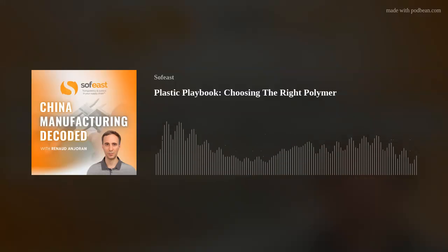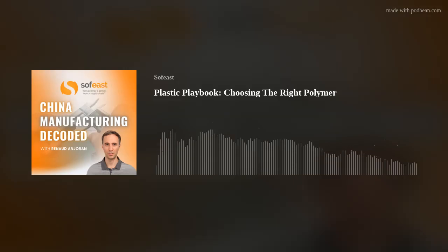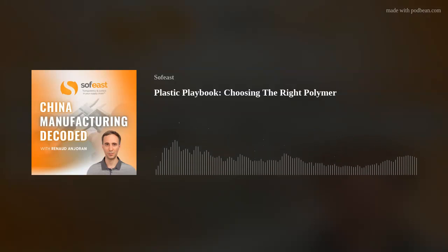Some of the limitations are poor UV and weather resistance. So if we're making a product for an outdoor environment, we wouldn't necessarily go with a pure ABS polymer. The heat resistance is not as good as some of the other polymers, so that's something else to be careful of. But some of the good applications would be, like I mentioned earlier, consumer electronics products, automotive trim, enclosures for various products, including the famous, dare I say, the Lego brick. So all of these products are very good all-round products used from the workhorse polymer.